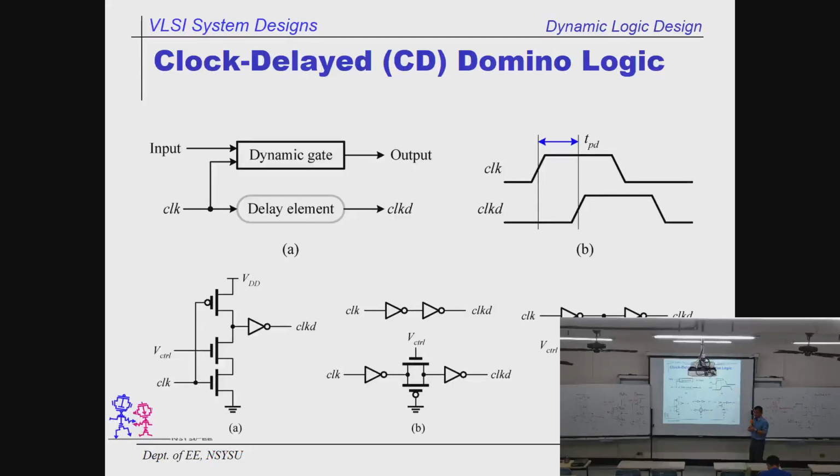And the more clocks you use, okay, I told you before, I was afraid of too many clocks because you have a synchronization problem. So there are 3 ways to do that. The first one is I use a control logic. This is an inverter. Okay, when it is on, then you have inverter after inverter. So the clock is delayed by 2 inverters to become the clock D.